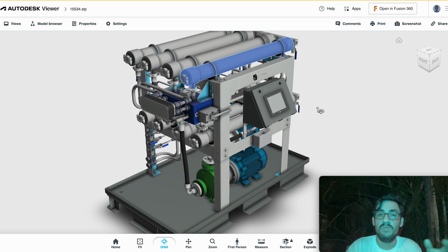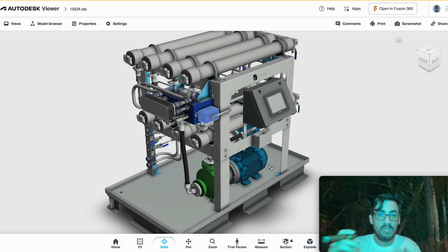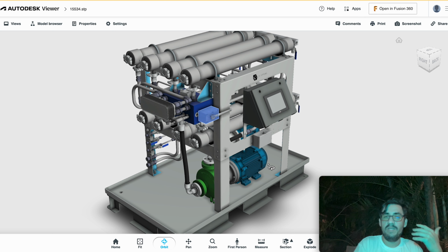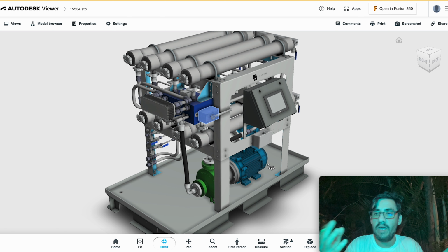Or we have these types of machines that have 2 sets of tubes in the same machine. But because of limits on pressure, the pressures on the different membranes, they're very specific to the membrane, and there's just really no way to have like a stage, like first solvent recovery, then winterize. It doesn't really work. So what we do is we have a valve. And so you flip this valve over and you're going to go from winterization to solvent recovery or whatever, because the flow just goes from one set of membranes to the other set of membranes. And so it's a few extra bucks to add that duplex type of functionality, but that really does save you a ton of money and lets you have that flexibility of having 2 functions in one machine, if that makes sense.